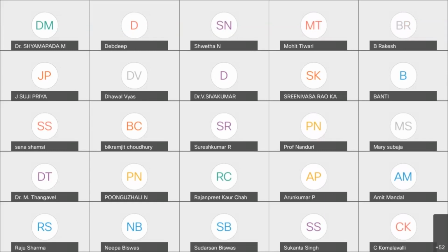Famous mathematical methods? You mean design techniques for PUFs, right? Yes, sir. Yeah, so there are different types of PUFs, in challenge response systems. I think the starting point for learning PUFs would be what is called an arbiter PUF.